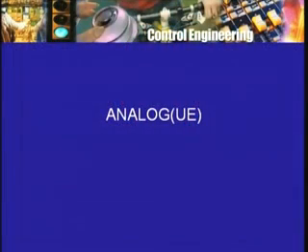It is a model in the sense it is an analog of the mechanical system. So you talk about an electronic or analog computer setup which will model a mechanical system. So this is not like the natural modeling based on similarity. The op-amp based system is not anyway like the mass spring dashpot system. It's made up of totally different things.